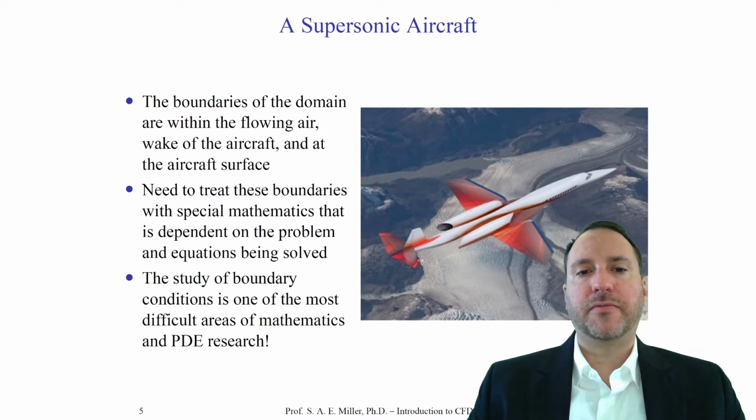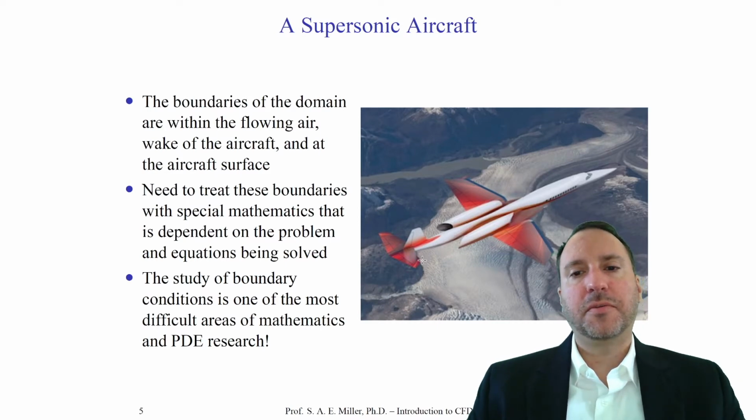That is where the velocity is allowed to be only parallel to the wall. In the Navier-Stokes equations, we would need to set the velocity to 0 at the wall. There are additional conditions for the boundaries at the wall, depending on these two sets of equations. Furthermore, all the other equations we looked at in the class might have modifications for these boundary conditions.